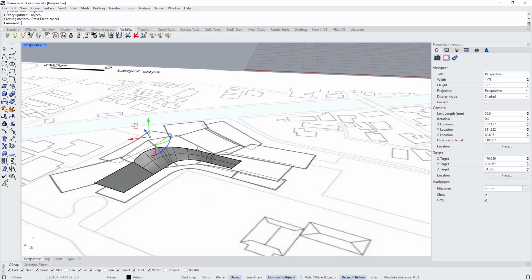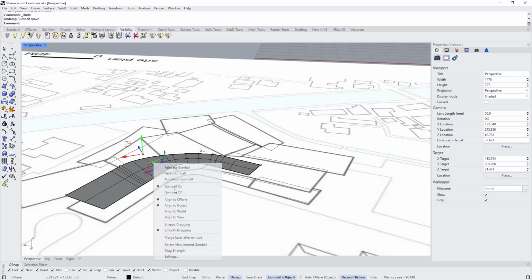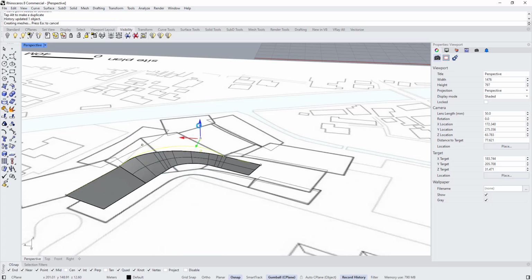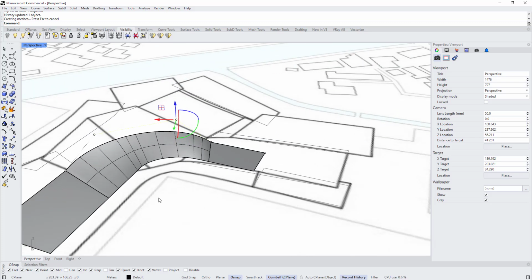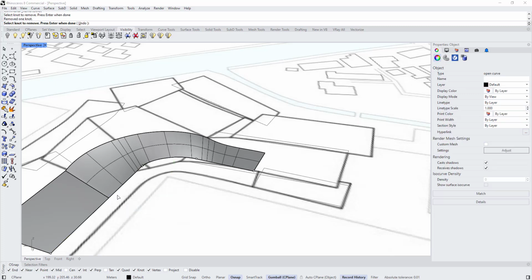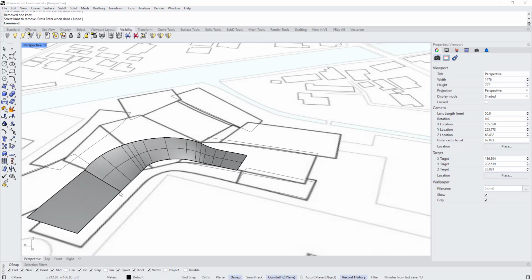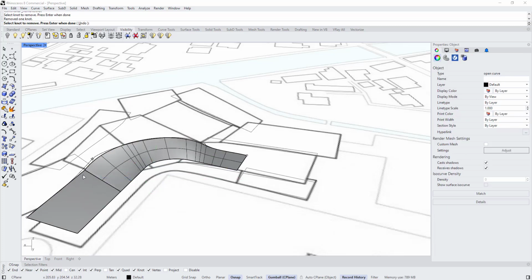Now, if I start adjusting these control points, as you can see, let's just set the point to C plane. The surface will update. Now, of course, there are some bad connections here, so I'm going to remove this kink. Let's remove this one. Click, and here too. Let's remove this one. Here, click. Okay, no, not this. I want to remove this series. Here, right click, remove this kink.